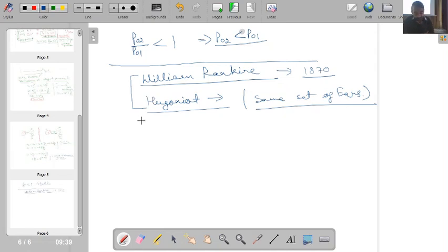Okay, however, in both of these mathematical formulations, they have not defined the behavior that the shock wave will always lead to compression. Okay, like we have seen just now thermodynamically, that if we consider Mach number less than 1, then we will not have a feasible situation. Okay, so mathematically we were able to find out that if we move from left to right across the shock wave, that is from a Mach number greater than 1 situation, then my P2 pressure is actually increasing over here. But if I move in the reverse direction, that is something which mathematically is open. Okay, so mathematically this condition was open, in which direction the flow should proceed while we have involvement of the shock wave.